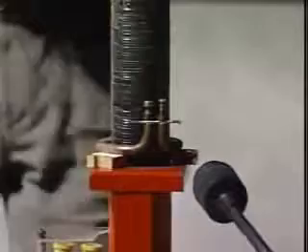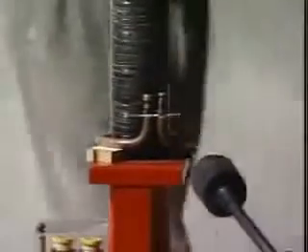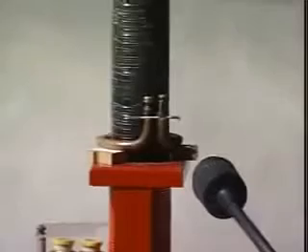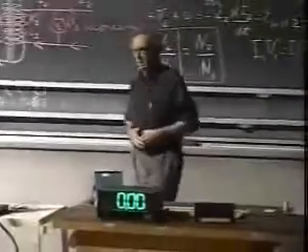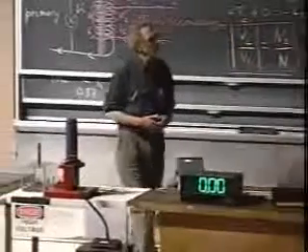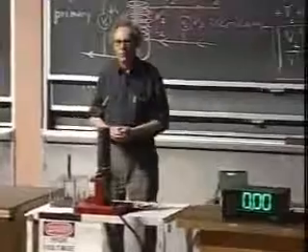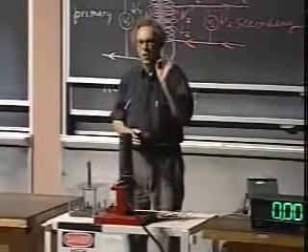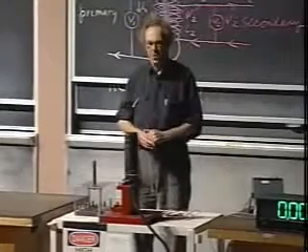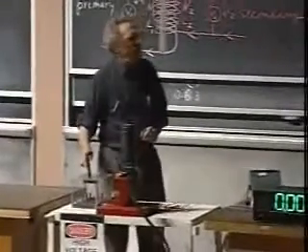And so now if I power the primary, I can't tell you exactly what the current is through the secondary, but it's probably somewhere in the vicinity between 500 and 1000 amperes. It will glow. It may take 1 minute to melt. It may not melt at all. It may take 3 seconds. Unpredictable, because we don't know exactly the resistance of that nail. So I will tell you when I do it.